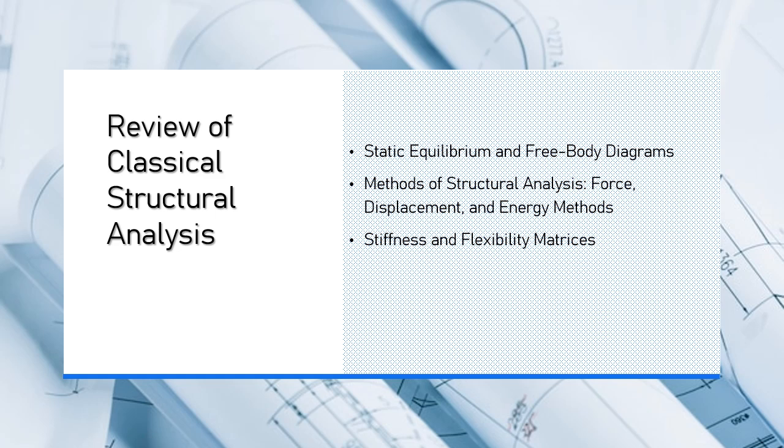Key features of displacement methods. Displacement methods are more suitable for analyzing complex structures like frames, trusses, and high-rise buildings, where static indeterminacy is present. This method works particularly well for structures that have many degrees of freedom. Example: in a frame structure subjected to a load, displacement methods help calculate how much the frame deforms and then use this information to calculate internal forces.